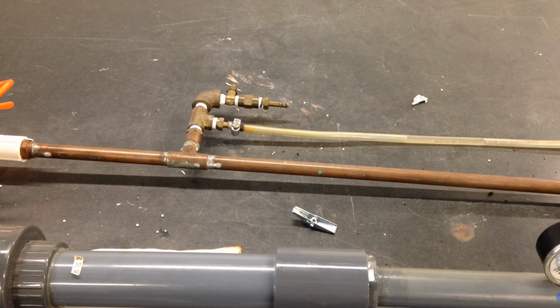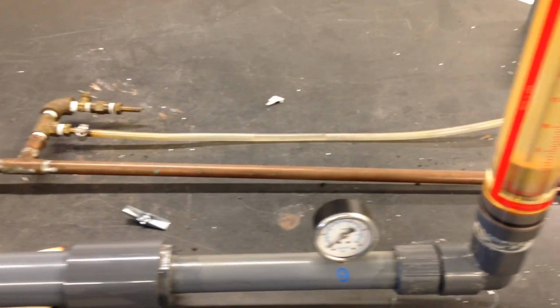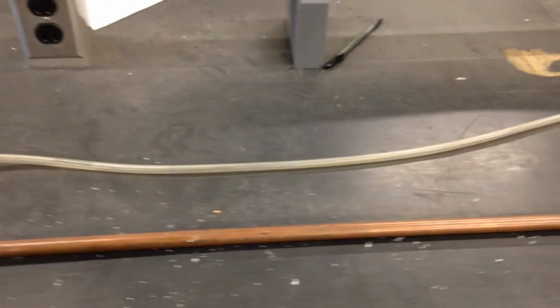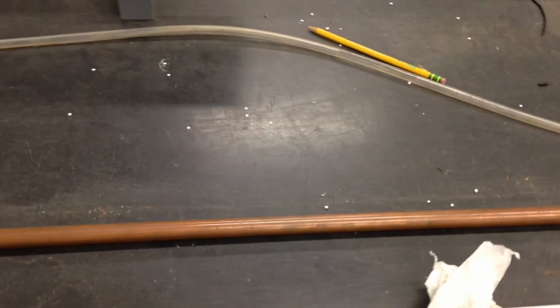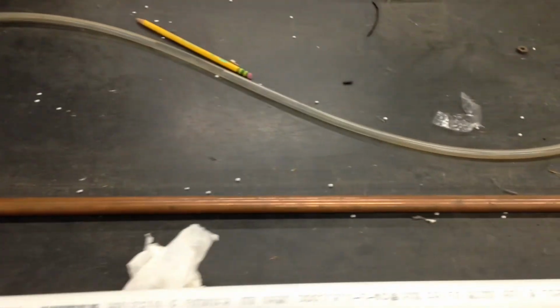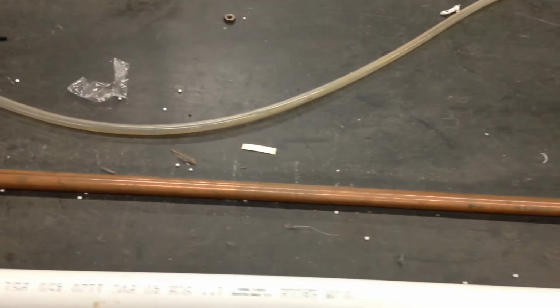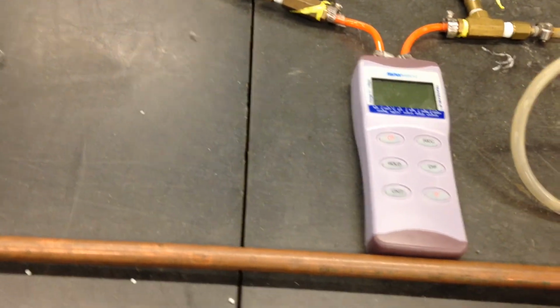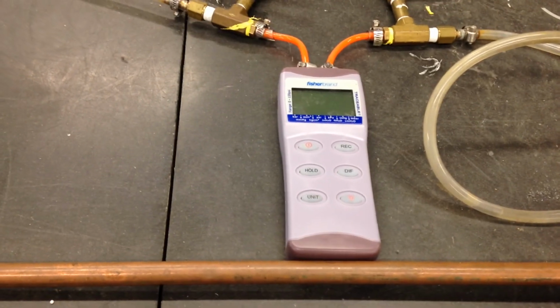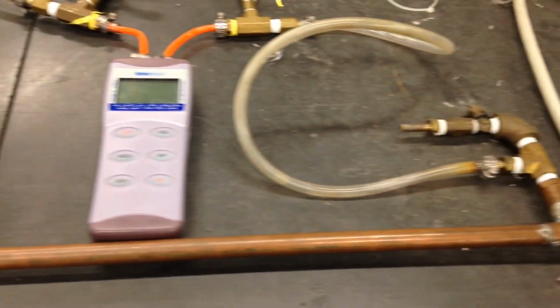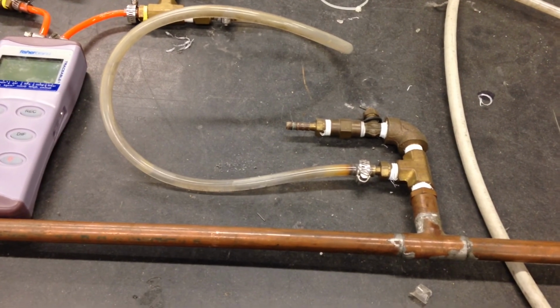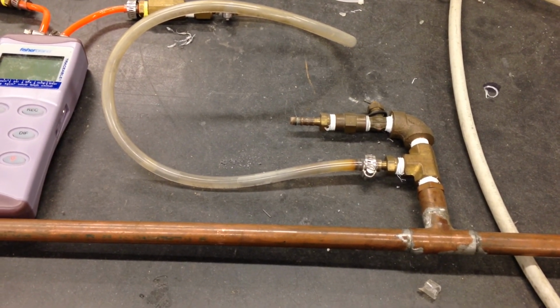The last is a Moody Chart test. We have this piece of copper tubing in the lower part. The upper part, you'll see what it's good for in a second. It goes across the breadth of the flow bench, and it reaches a point where we'll have a digital manometer. The digital manometer will record the head loss, again in inches of water, from one end of this to the other, or at least between the two taps. And all the dimensions will be given to you.